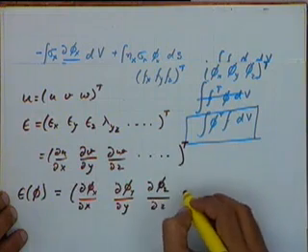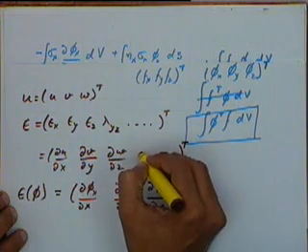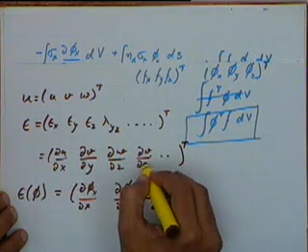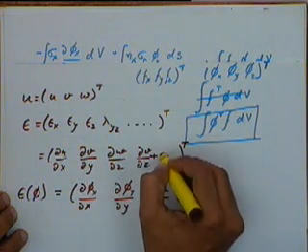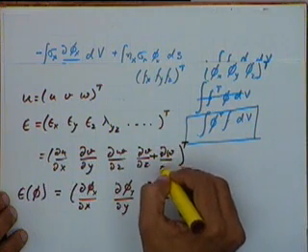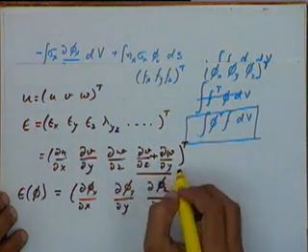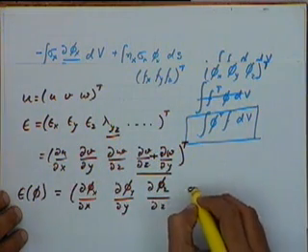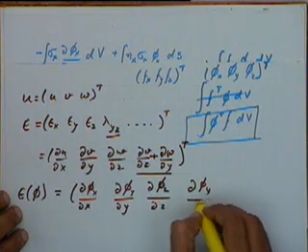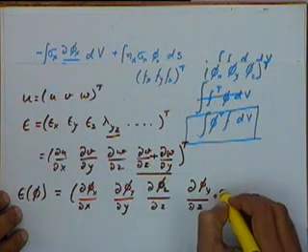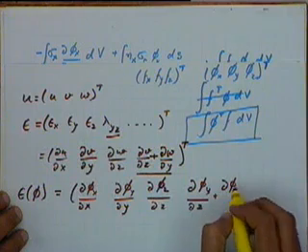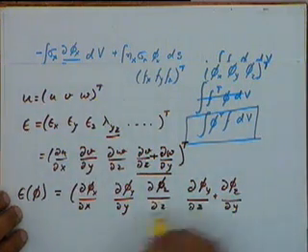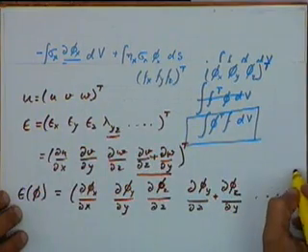The lambda yz term, here what we would have got would have been del v by del z plus del w by del y. This term would have been lambda yz. Corresponding to that we will get here del phi y by del z plus del phi z by del y, and another 2 terms like this.